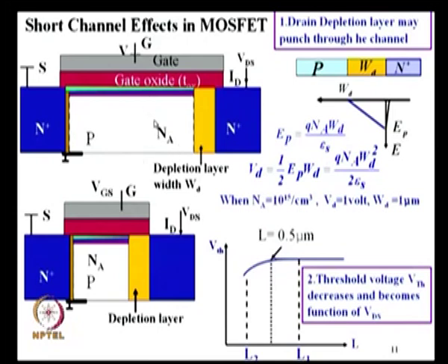Okay. So, you increase the doping concentration. That is why you go to 10 to the power 16, 10 to the power 17, but that has other repercussions like reduced mobility and increased threshold voltage. So, you reduce the gate oxide thickness, all those things are there. Now, if the channel length is 0.1 micron, even if you go to higher doping concentrations, it can deplete all the way, or at least partially.